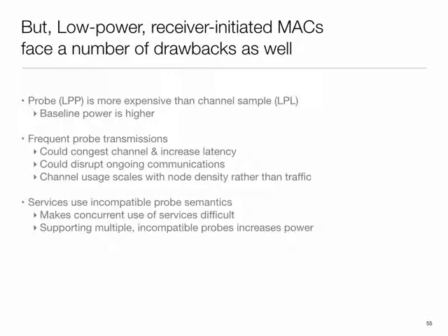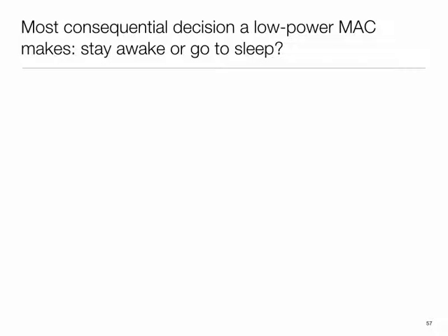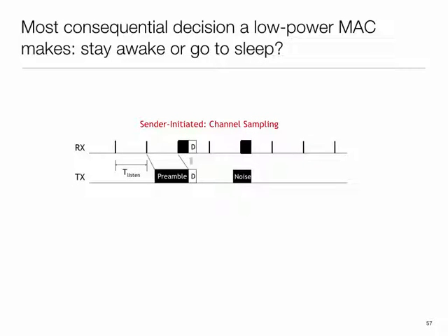Passive listening is certainly somewhat cheaper, even in short-range radios, than transmitting. The other thing is, when you're actually sending the probe, you're going to occupy the channel, so there's going to be wastage of bandwidth. So there are issues coming up. But if we could somehow design it, it carries some advantages.